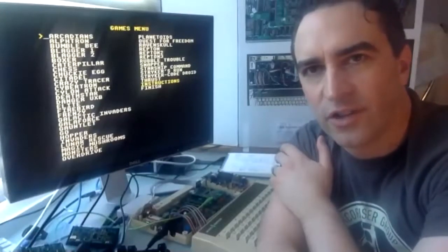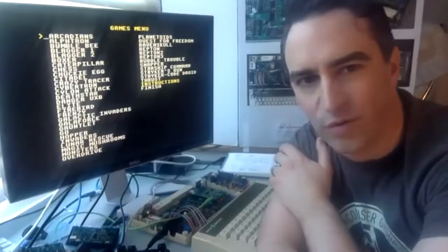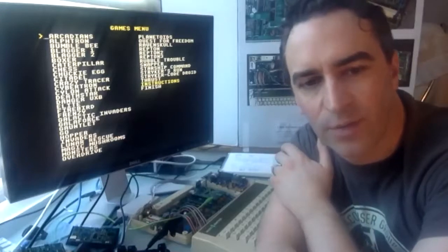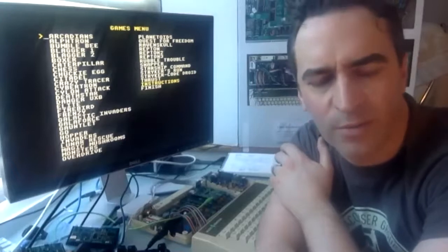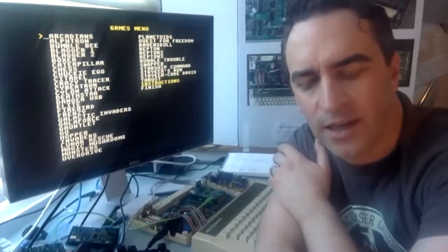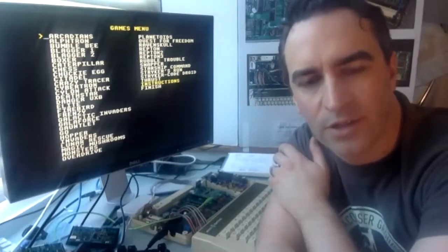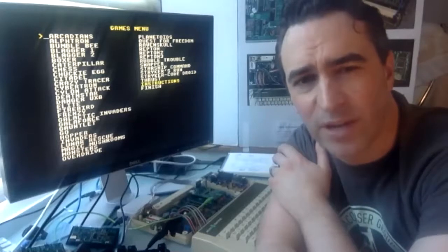Partly this is exciting because the DAC needs a ton of passive components hanging off the side for power conditioning, and there's something like a second order filter on the output of it. And also it uses quite a few pins from the FPGA. If I could ditch this, then maybe this could give me a bunch more pins for the VGA output.